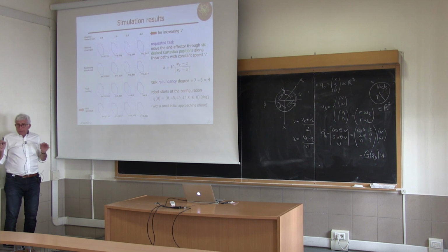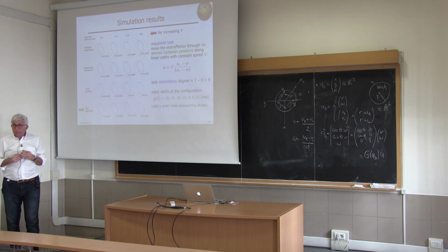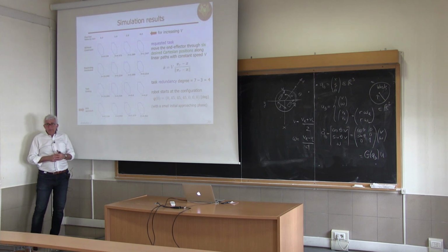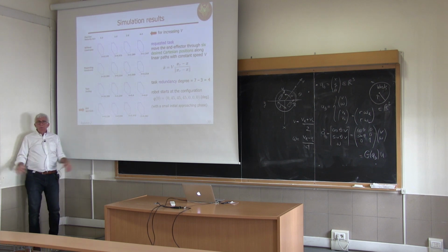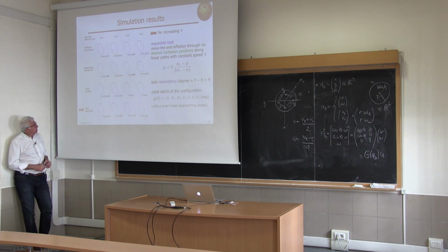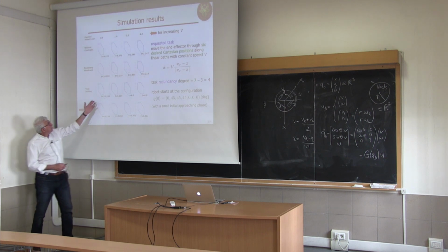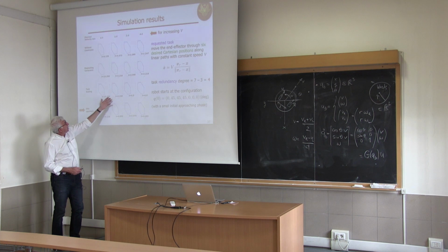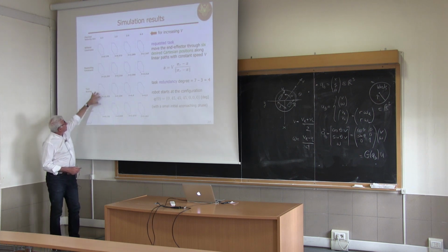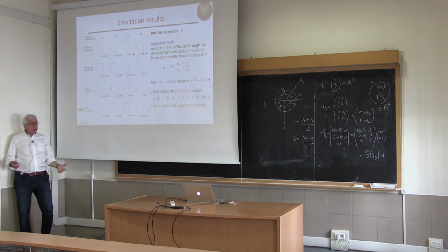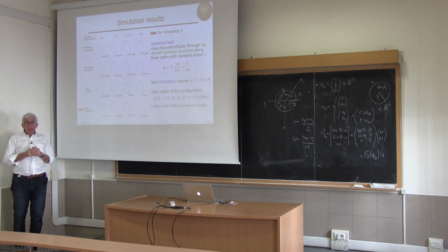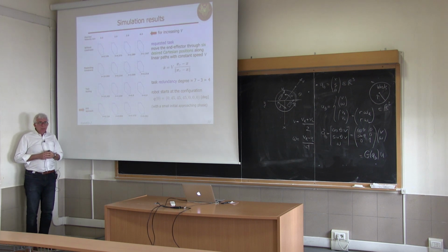If you do simple task scaling, in the sense that we have seen in the previous example, you're just reducing the speed because you realize that some joints are saturating in velocity, so you slow down all the joints at the same time. Then you see that you obtain larger times. Still, on this side of the hexagon, you're making some error, because this task scaling does not take into account the presence of limits in the joint range, which cannot be scaled.